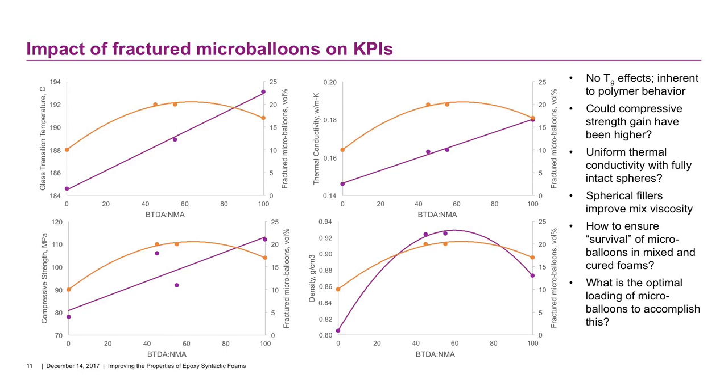With regards to glass transition temperature, we do not expect any effects here because that should simply be inherent to the polymer behavior and should be independent of any fillers which are in the system. So we believe the data as originally generated stands. The compressive strength data to the lower left could certainly be influenced.